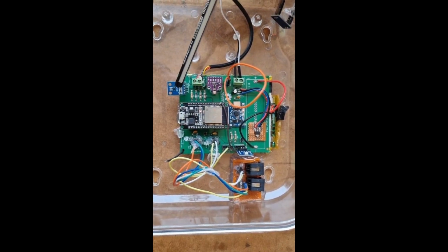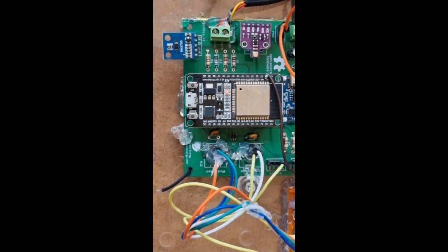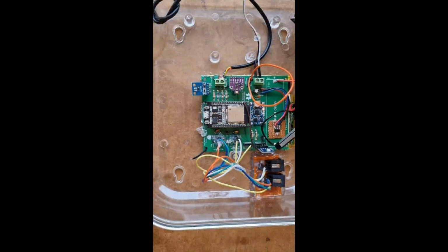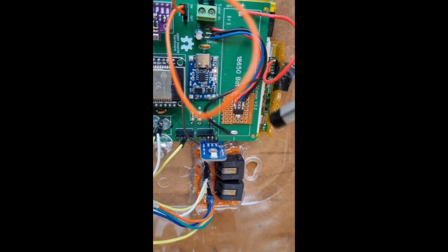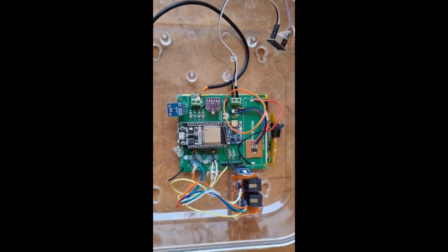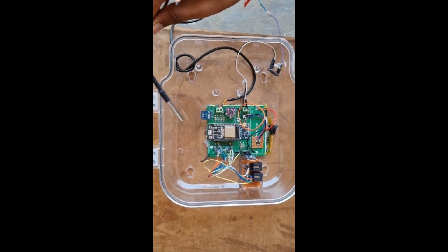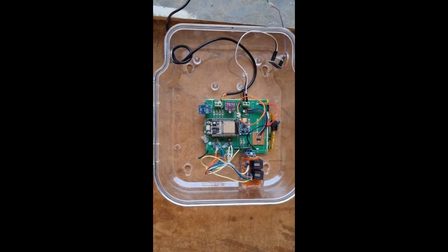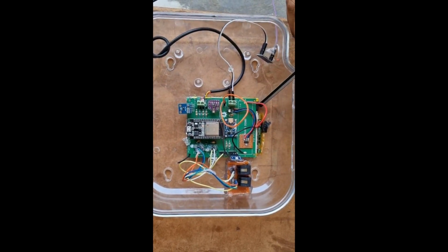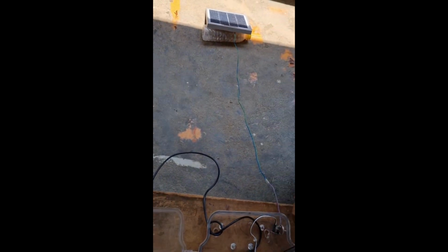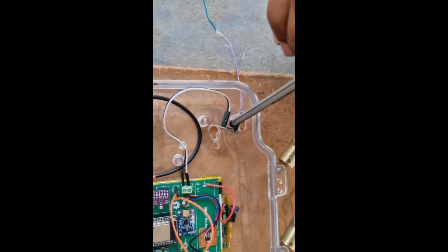This is a BH1750 sensor. It is also known as a lux sensor. It measures the lux level of an environment. And this is a UV index sensor. It measures the UV rays from the sun. And this is an external temperature sensor, also called an ambient temperature sensor. It measures the external temperature. We have also connected the whole system with a battery and a solar panel. It is a rechargeable battery, recharged by the solar panel, and the solar panel is connected through a voltage regulator.